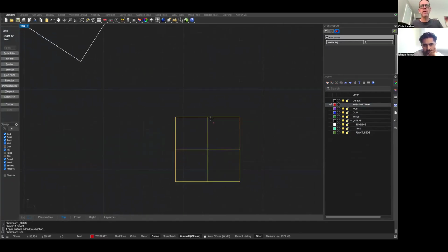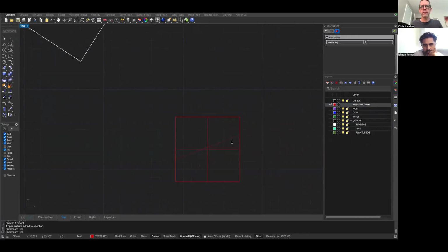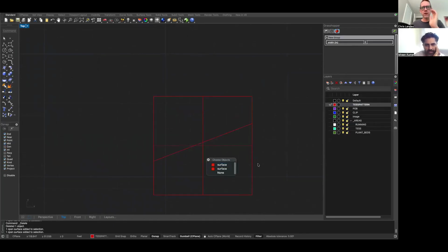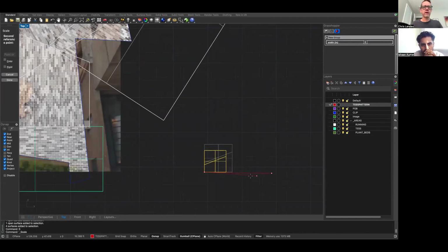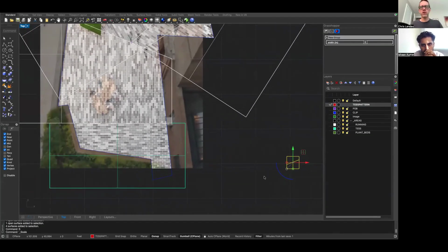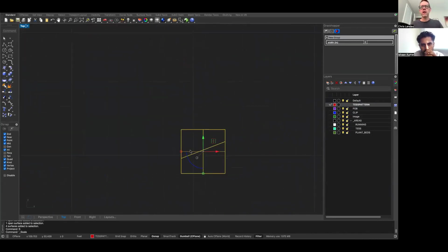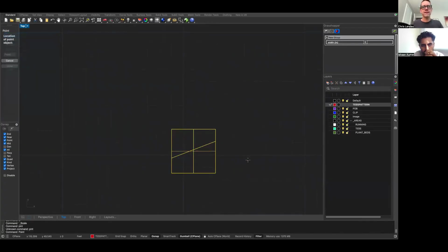Now I can take this and draw a line, and split it in half, and then we're also going to split it sort of this way, right? So we take this and we say split. We select those curves, hit return, and now I can delete the curves. We have these shapes, right? Would there be four or five? Did it split? No, no, you're right. I'm just getting deceived by the iso curves. It's all good. So we'll take this, and right now the scale is probably not right, so I'll scale that as well. Under normal circumstances, we'd be measuring everything, but we don't need to do that here. So then we have the pattern, and we have the point at which this pattern is going to start. So we have the origin point.